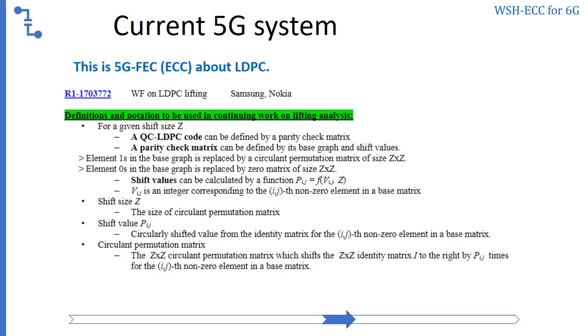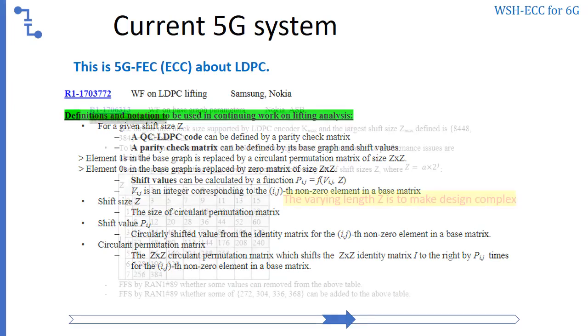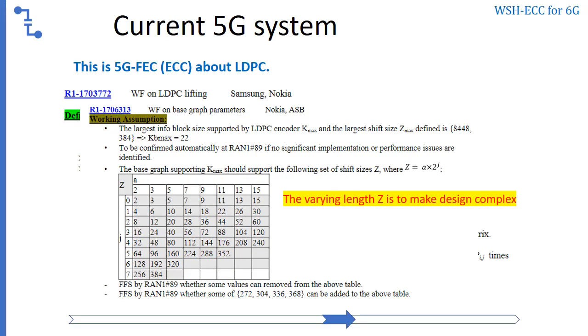The second question is its flexibility, how to meet different lengths among all modes. Its idea uses lift size to change the size of the matrix. Such problems can make digital design complex. Designing multiple similar barrel shifters and muxes makes placement and routing complicated. My suggestion is to use a fixed size, such as the QC_size variable I define to the power of 2, such as simply 64 or 128, and then design different lengths as multiples of QC_size without changing QC_size. The design process then uses fixed size floor tiles at the floor plan stage.